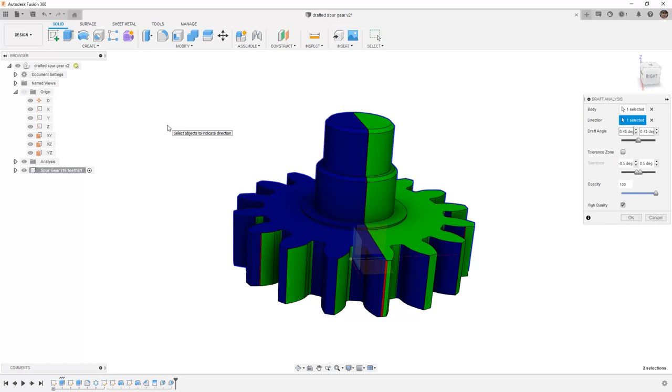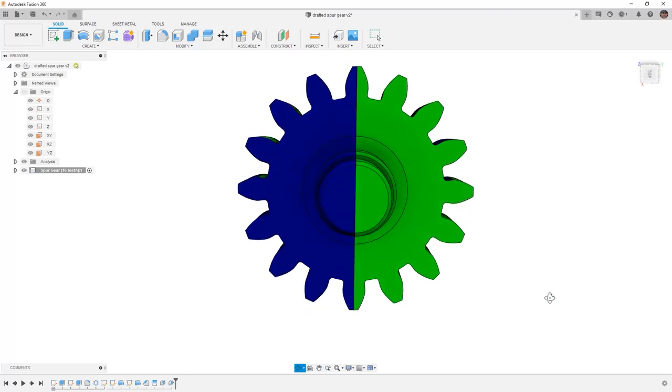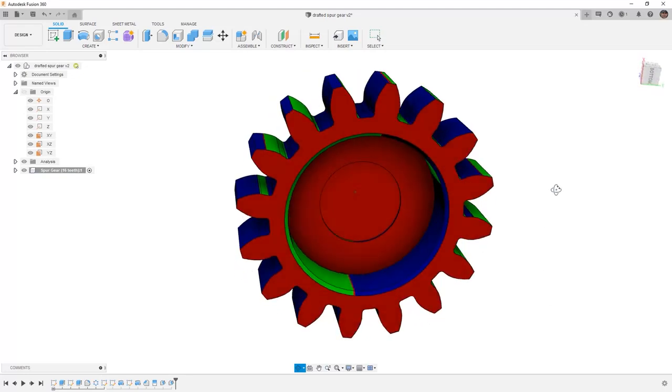When we're talking about a shaft where we have a rounded section coming directly up to the parting line, the majority of that shaft has plenty of draft on it. But right at the middle, or right at the parting line, oftentimes you will have a slight problem. You can get around this in most cases by talking to the manufacturer and seeing if they can actually draft or use a part that's undrafted around the round section. If they need a draft, we can always put a small flat section there and still have the functionality needed to actually support the bearing. In our case, everything looks pretty good, so I'm going to say okay, and just verify that I have applied the draft to all the areas.